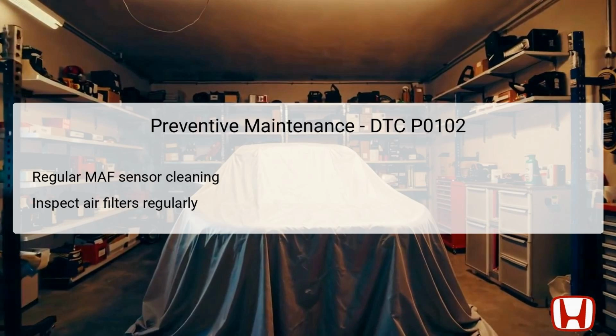Additionally, ensure that the air intake and air filter systems are kept clear of contaminants. Inspecting and replacing air filters as needed will prevent debris from reaching the MAF sensor, thus prolonging its operational lifespan. Implementing these preventive measures helps secure optimal engine performance and fuel efficiency over time.